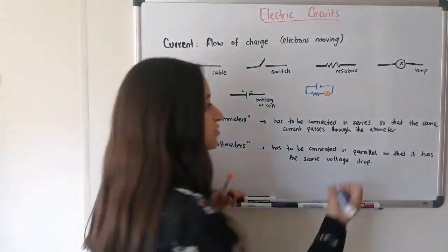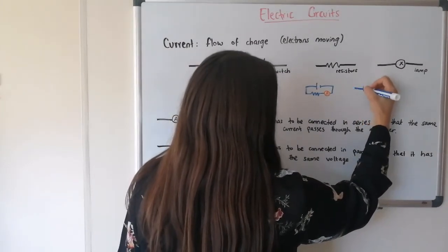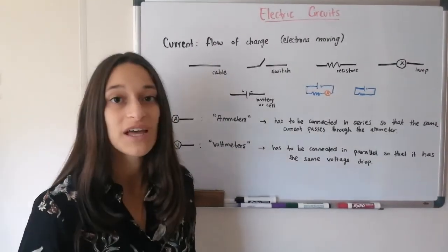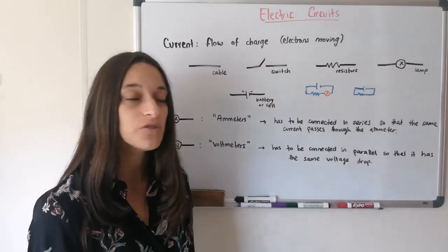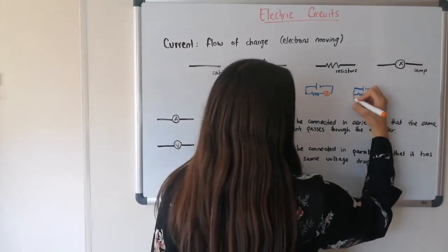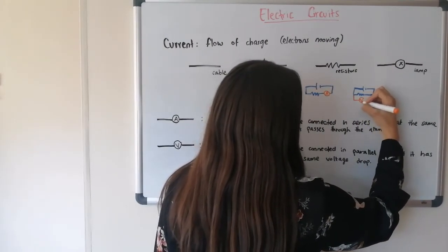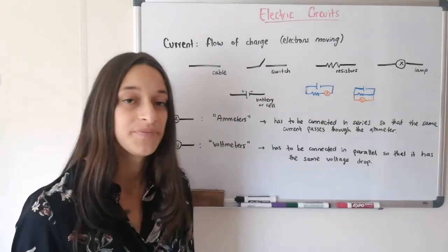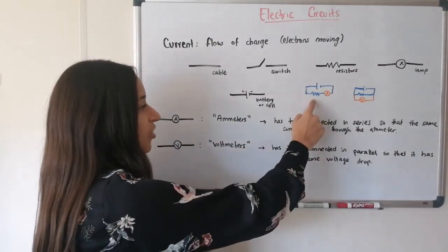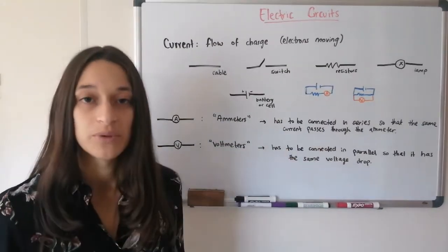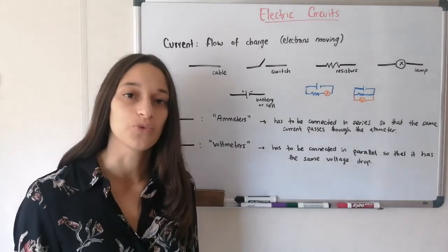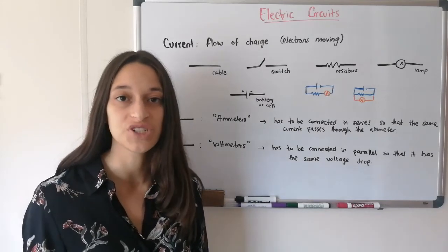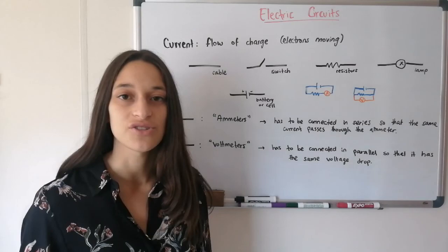Now, if you wanted to measure the voltage, let me draw it again, you can't connect it in series. You have to connect it in parallel. That means making another branch with the voltmeter. So that means something like this, making a branch with the voltmeter, and that'll give you the voltage around the resistor. Right, so that's the way to measure current and measure voltage in a component. Now let's move on to the circuit rules, the rules that a circuit always follows that tell us what the current and the voltage can be when we analyze a circuit logically.